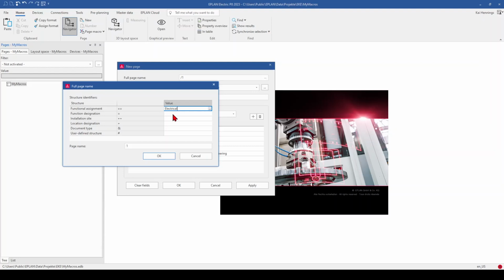start with electrical. And then, for example, the manufacturer, like Siemens. And then we go to the devices. For example, we want to have PLCs or conductors or low voltage distribution devices, whatever. I select here the PLC and then, for example, the type of PLC, for example, ET200SP or the S7-1500 or ET200 Pro, or you can also have here frequency converter and so on.